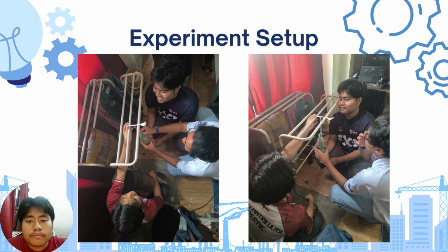So, our group assumed 1 milliliter of water equals 1 kilogram of mass. A measuring bottle was used to measure 100 milliliters before putting it in the water bottle. The corresponding vertical deflection at the middle of the spoon was recorded. The steps repeat until the spoon fractured.